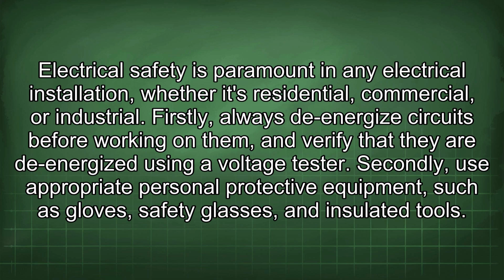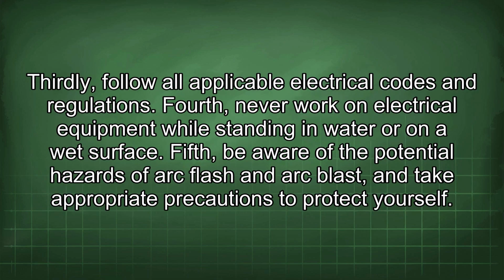Electrical safety is paramount in any electrical installation, whether it's residential, commercial, or industrial. Firstly, always de-energize circuits before working on them, and verify that they are de-energized using a voltage tester. Secondly, use appropriate personal protective equipment such as gloves, safety glasses, and insulated tools. Thirdly, follow all applicable electrical codes and regulations.